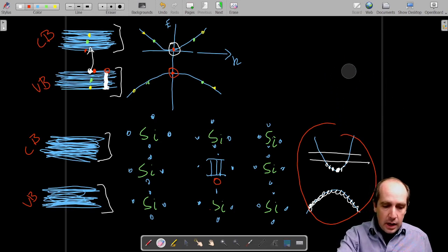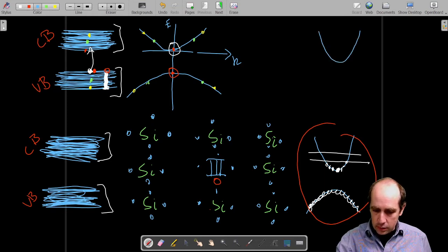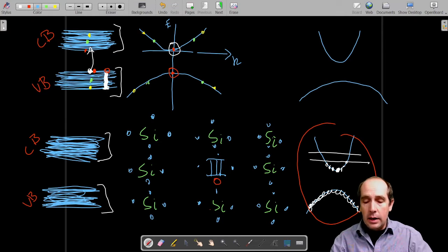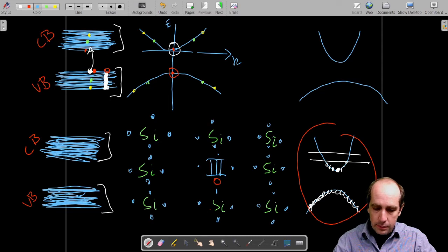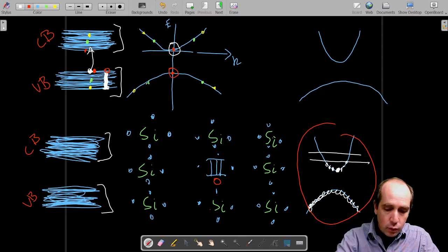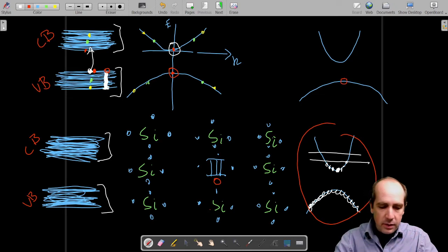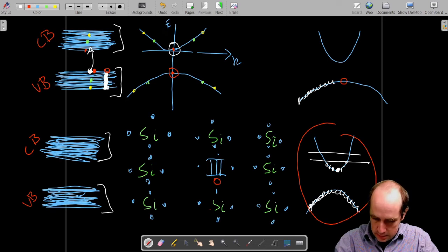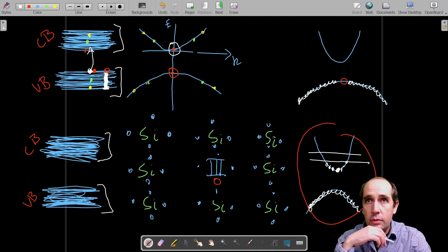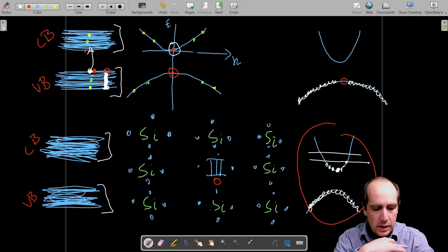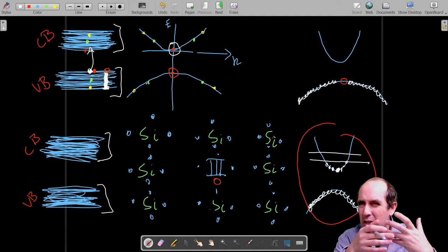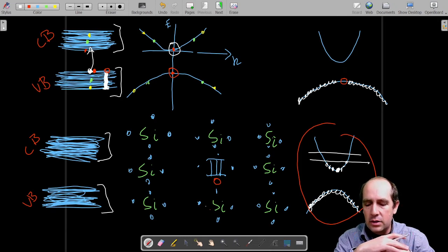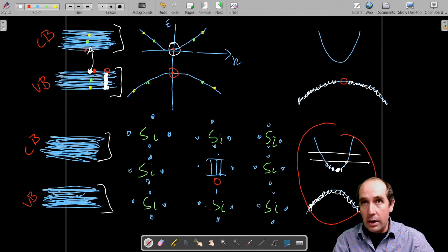let me just make a little bit of space here. What we will have is that now the conduction band and the valence band, in the case of the group 3 dopant, is that if we just put one single atom, again, this state will be vacant, and all of these states will be full. Again, strictly speaking, this means that what we used to call the valence band, strictly speaking, should be called the conduction band, because it's no longer full. We don't change that. I mean, we keep calling it the valence band just for convenience, because really the conduction band is the one on the top, and this one will really be a conductor that will conduct electricity by holes, not by electrons.